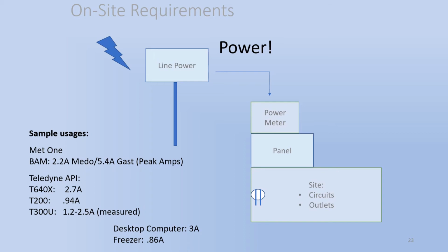The standard for most household circuits are rated at either 15 amps or 20 amps. An important point to remember is that circuit breakers should only handle about 80% of their overall amperage for periods longer than 3 hours. That means a 15 amp circuit breaker can handle around 12 amps and a 20 amp circuit breaker can handle about 16 amps.